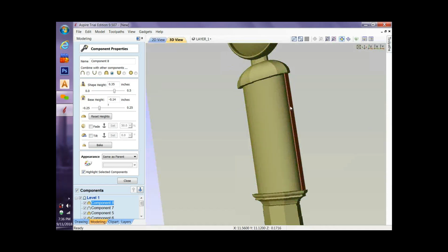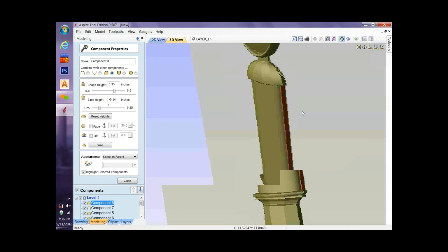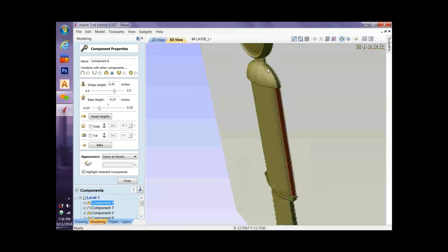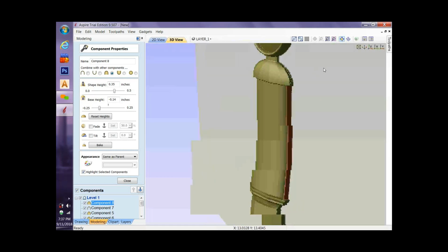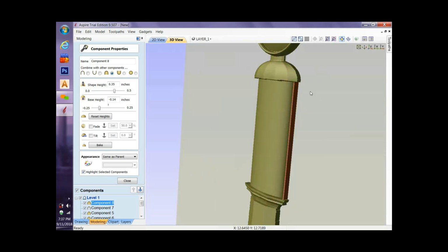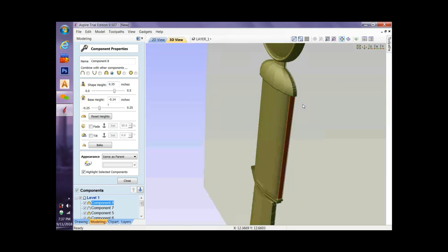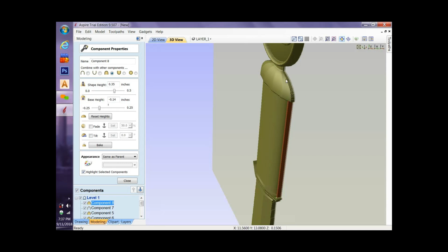Now, I don't know if you guys cut a lot of models. The problem I have with models is the higher you go, of course, the longer your bits need to be. And now you have a straight side like this. Those tapered bits that everybody raves about, they have their purpose. But to get these flat sides, the 90 degree, you're not going to get it with a taper. So what I always try to do is I know the cutting length of my smallest ball nose, and I try to make my heights accommodate that so that my ball nose can always run right up to it, then straight up, and then keep going and do the design.